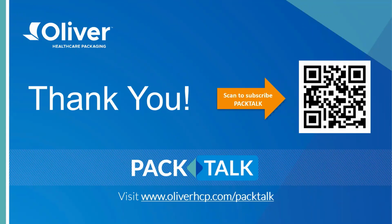the test methods and standards, but there's different ways to do that with porous substrates versus non-porous. So I've seen plenty of people using the dye penetration test with paper. It can be a little trickier with the absorption and wicking that can happen with paper. I've also seen people use the bubble leak test, but certainly medical papers are used and have been used prevalently for sterile barrier systems for many decades. So I think there's ways to check integrity.